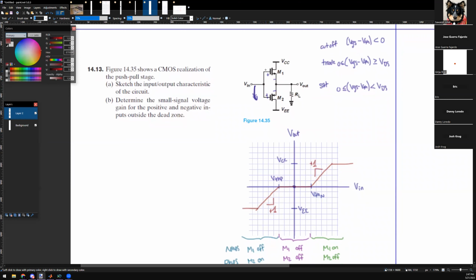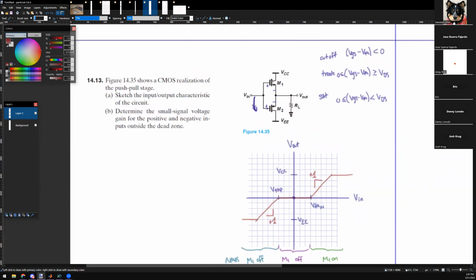If you do this other one, remember these circuits are only valid when you are in saturation. The purpose of this one is trying to extend the range of saturation. This is in saturation, this is in saturation, these are not, but unfortunately there's a gap between the two. So you have a nice wide range of rail to rail saturation. What do I mean by that?